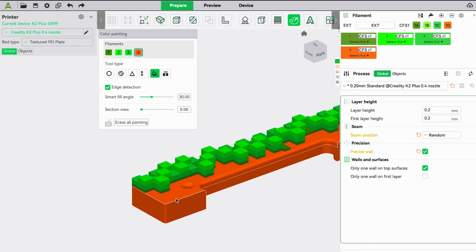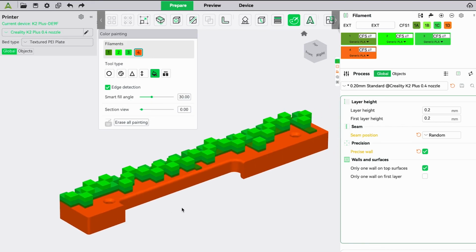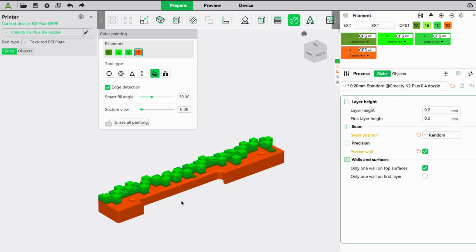My suggestion in this case, if you want to have as little waste from the printer as possible, is to do it layer by layer, because if you have different colors on the same level, or you have, you know, green, brown, green, brown, green, brown, each time the printer will change a filament and each time it will create waste. But it's just my suggestion.